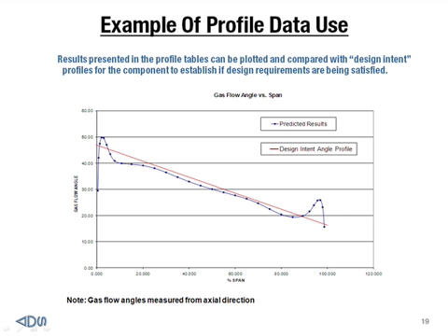And you can see the dots on the blue plot are the individual points. And you might notice that at the end walls you see a very funny, abrupt swing in air angles. What you're seeing there is the end wall secondary flows at the root and tip of the passage. These vortex-like flows have very strong angle changes, and it's very well documented in the turbine literature.